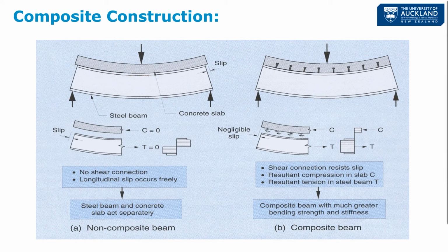And that's reasonably common, particularly if you use a precast concrete floor. But what it means is that you're going to need a slightly bigger beam in order to carry those loads.